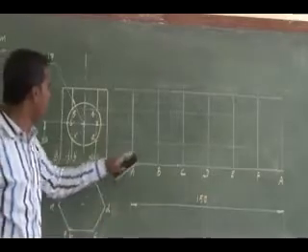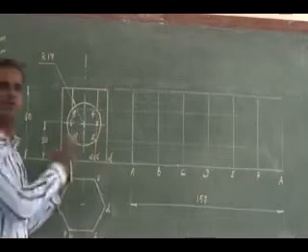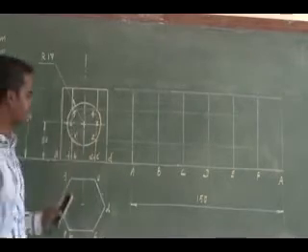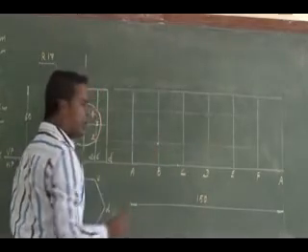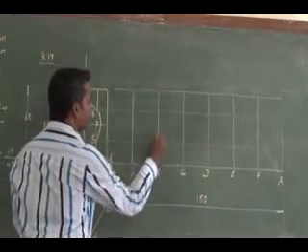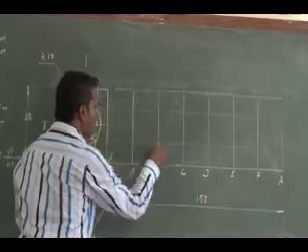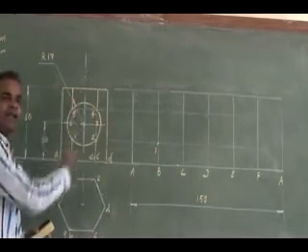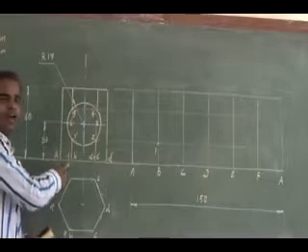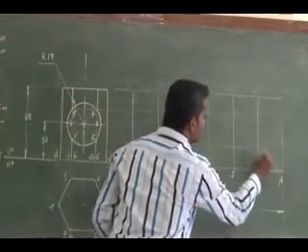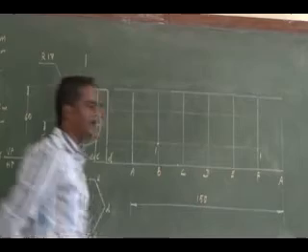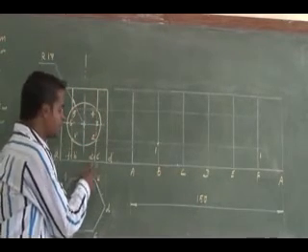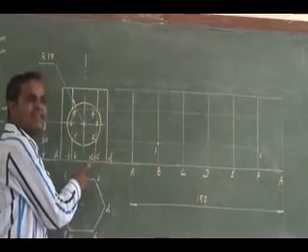Listen all of you. Cutting point 1 in the visible face is exactly on the B vertical edge. So on B I have to mark my cutting point 1. Similarly, the same cutting point 1 is available at the hidden vertical edge behind, that is F. So here at F I have to mark cutting point 1 again. Similarly, cutting point 2 is available at 2 locations: visible edge C and hidden edge E.